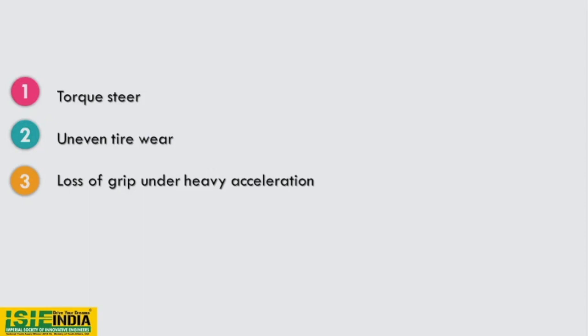Then there is a loss of grip under heavy acceleration, like if you are turning the vehicle and due to misalignment or torque steer, our balance shifts to one direction, and it tends to lose grip and it tends to slip also.